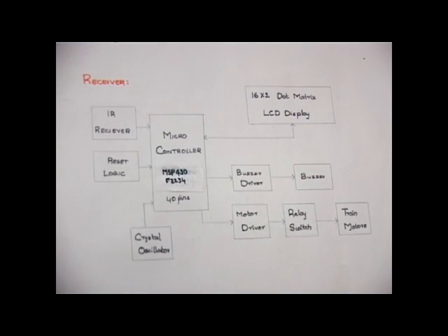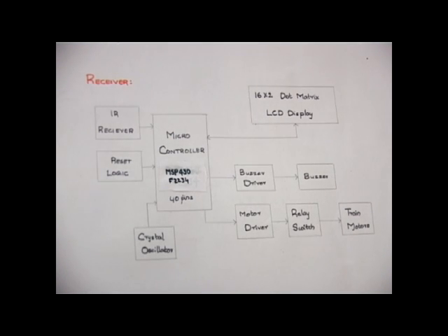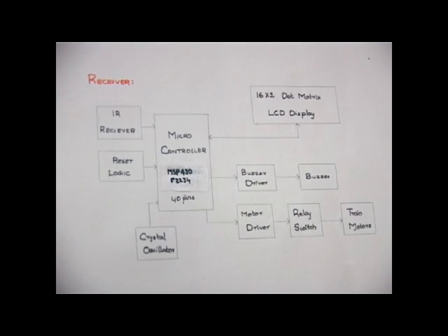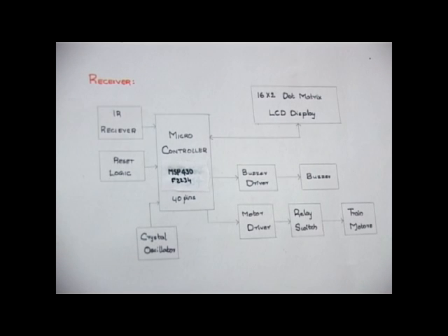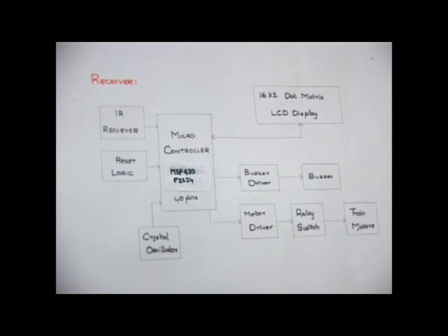Now coming to the speed control of the regulator switch. The speed regulator is constructed with 2 relays operated with 2 transistors, which are connected to the output port of the microcontroller. By using these relays, the motor of the train can be controlled. Thus, the speed of the train can be controlled by using the signals detected in the transmitter part.